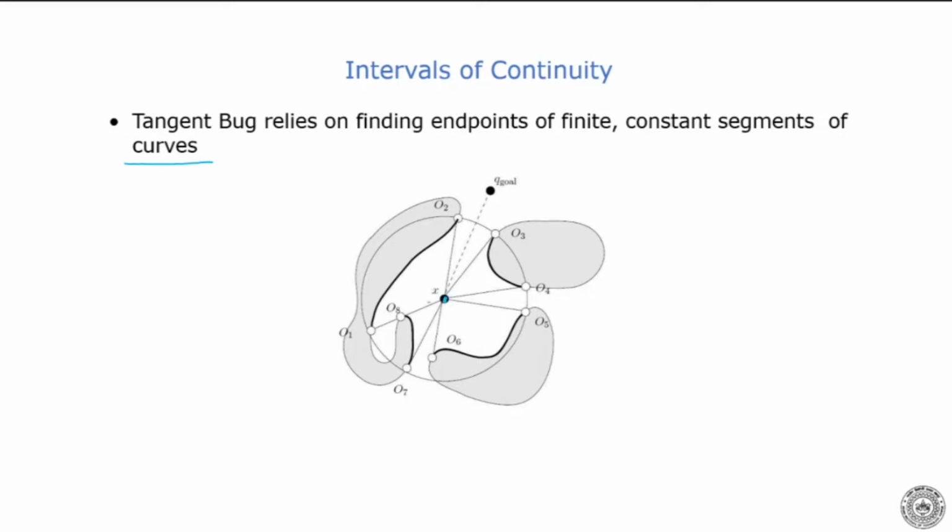It is sweeping from theta equal to 0, and wherever it gets the obstacle, you get a distance there. As we have seen, the way an ultrasonic sensor works is that if it hits the obstacle, the ray will come back and then it knows the distance of the object. Okay, now what it has done is it has given us these distance functions, and we know that this is the profile of the object now, because I know the corresponding distances of every point on that object with respect to x.